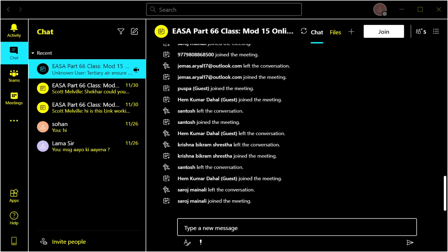Okay, so that's a basic sort of setup. In red, there's your high pressure feed oil. The green oil is the return, and then the white here would be your air and oil mist. Okay, and that's a basic tank. They all do vary, obviously, but they pretty much do the same job.